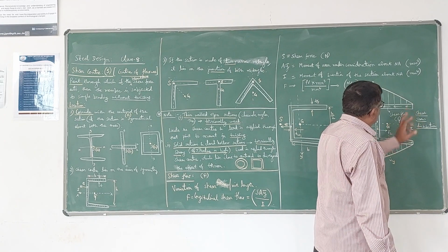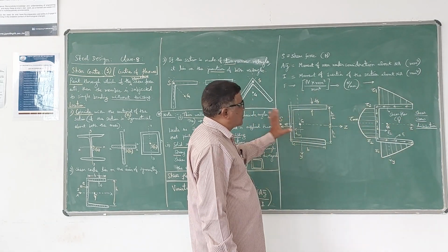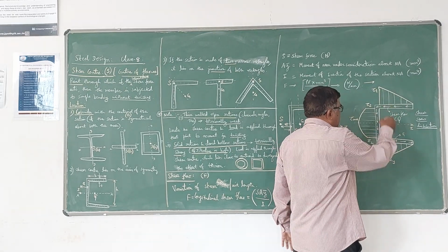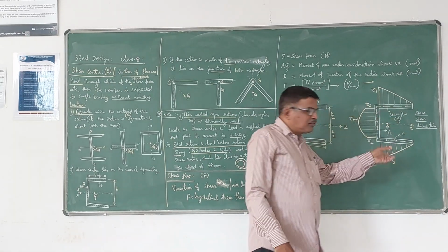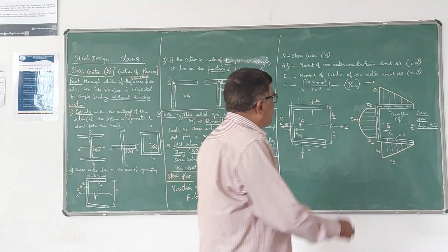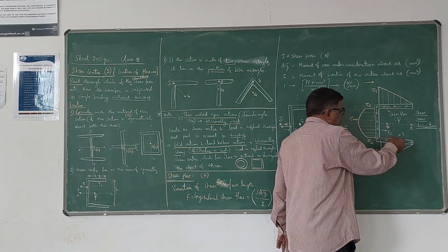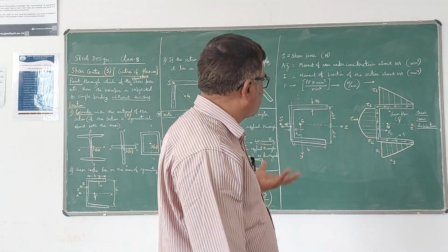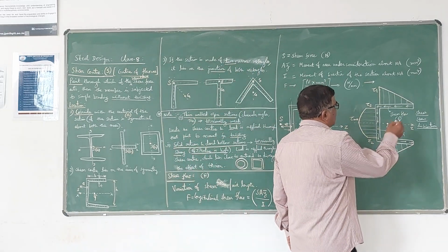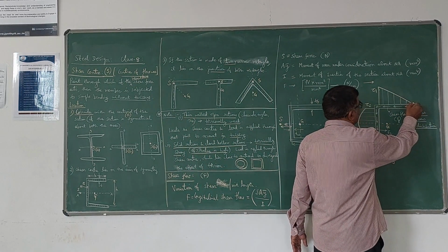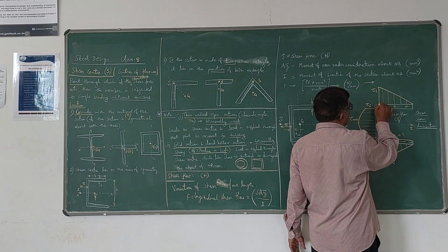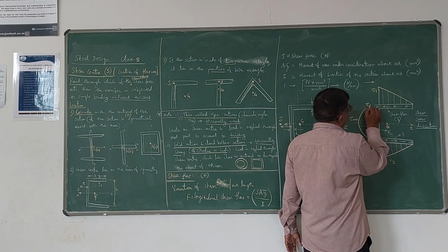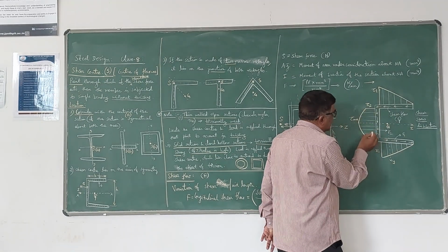Now, if you show the shear stress distribution for this section, if F1 is the shear flow in the flange and F2 is the shear flow in the web, assuming the direction of shear flow like this, when this is subjected to torsion, shear stress is a resultant of the torsional effect. So if you plot the shear stress variation, it will be 0 here, it has some value tau 1 at this edge, and here the value at this edge for the web portion, tau 2, and tau max will be somewhere here at the neutral axis.